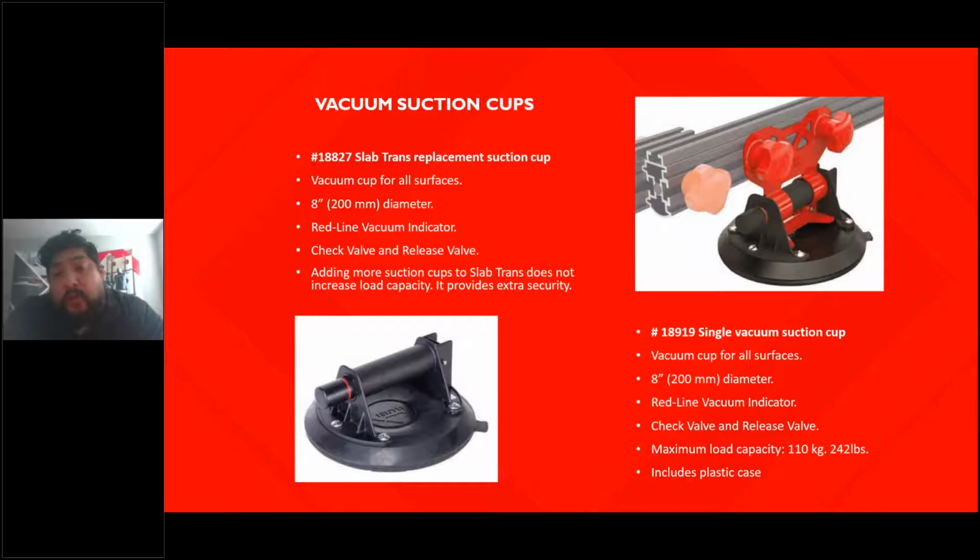Please be advised though, when we're using our suction cups, whether it's the Slim Easy Trans or these vacuum sealed suction cups, we have to clean the material off. We have to clean the suction cups to make sure we don't have any dust. If you have any dust on your material or any dust on your suction cups, it creates a bond breaker, and then you won't get a tight bond with your materials. When you go to move it, it can fall off or slip off, and you'd have to repump your suction cups. So please make sure to clean your slabs and your suction cups.